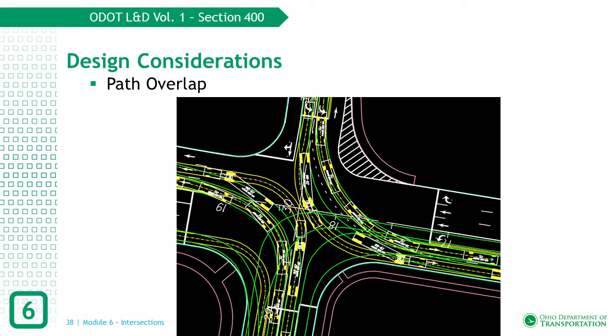This wasn't done because of the eastbound to northbound left turn lane like would normally be, but rather because the southbound to eastbound left turn lane had to access the receiving lanes on the east leg of the intersection. Shifting the southbound to eastbound left turn lane's stop bar to the south would not have allowed the turning vehicles to access their targeted receiving lanes and would have substantially increased the size of the intersection. All movements should be analyzed not just for geometrics, but also for intersection capacity, because in this example, the intersection area became large, creating a need for a longer clearance interval for the turns to complete their movements.